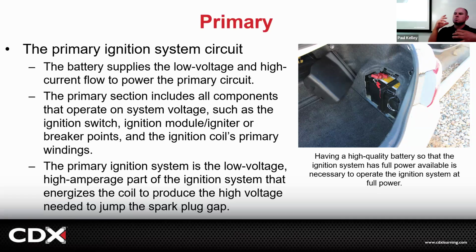So if my heated jacket is pulling the battery voltage down because the alternator is failing, and I disconnect it, the voltage would jump up a little bit, right? And it actually ran a little better. So I was like, ooh, my system voltage is down. That means the primary voltage is less. That means the secondary voltage is less. And under high throttle acceleration, it needs very high secondary ignition voltage, and it didn't have it.